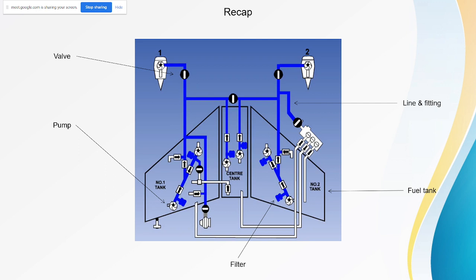Next, there are also filters installed at each pump to stop debris or foreign objects from entering the system. And lastly, we have an oil heat exchanger installed in the system. Although it is not shown here, it is used to reduce the oil temperature and also increase the fuel temperature. So next, we will look into refueling and defueling.